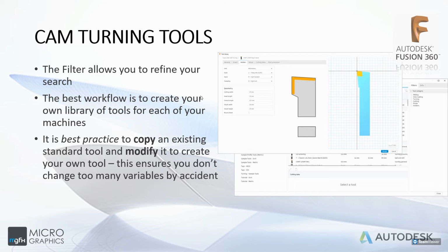Again, I'm going to stress this one more time. Best practice is to copy an existing standard tool and simply modify the dimensions rather than create it from scratch, because there might be some important data that you've missed or that you've entered incorrectly that will cause problems for you later on. And I will show you exactly how to do that when we get to the live demo.